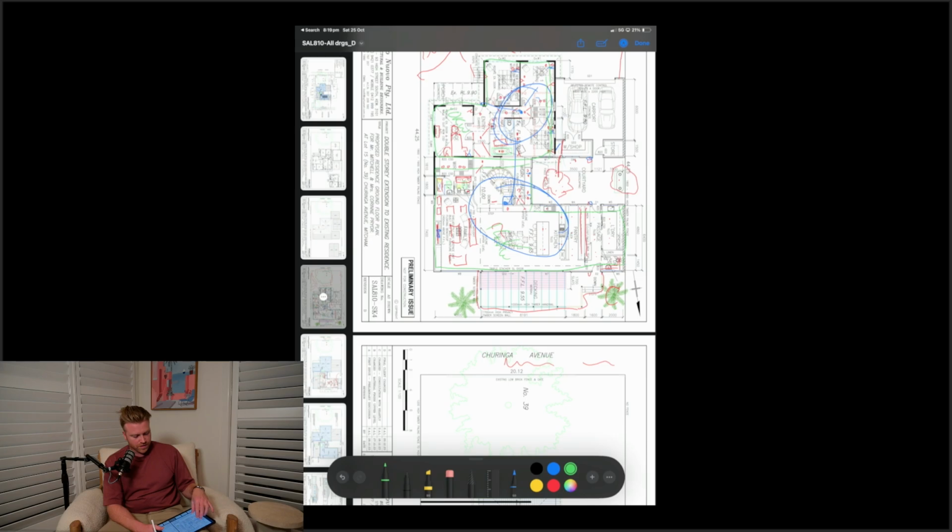So in winter, the front of the house will probably run a lot more than the back of the house just because of the south facing aspect. Upstairs probably wouldn't even run at all because a lot of that heat would rise through the void into the upstairs space. So maybe only just utilizing the fan. Where if you had a 21 kilowatt, it'd just be running the whole house all the time. So you'd have these spaces where upstairs would just be cooking. Even if you did baffle it down, you're still pushing the air elsewhere. So it's just running more effectively when you've got those 3 units. So yeah, it's a good compromise when it comes to price.